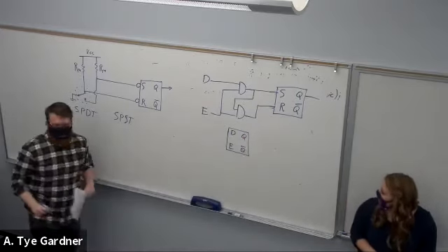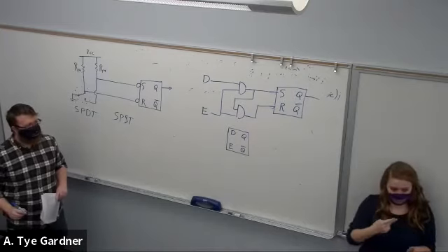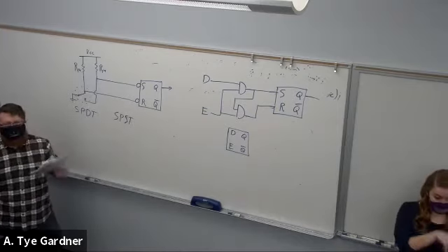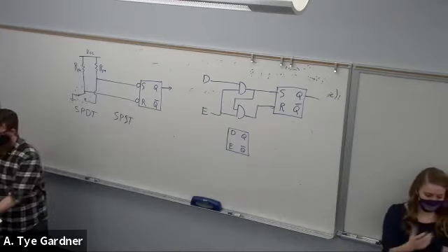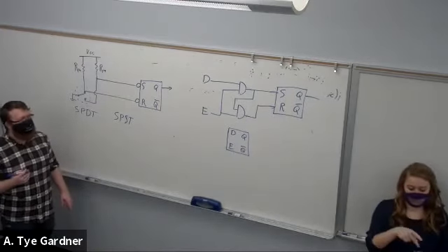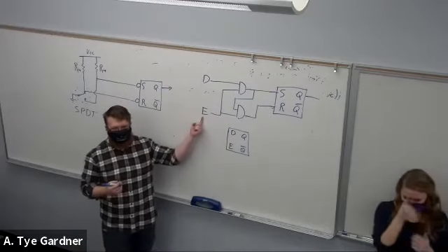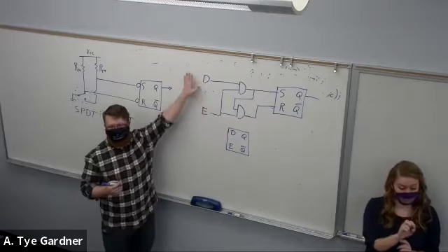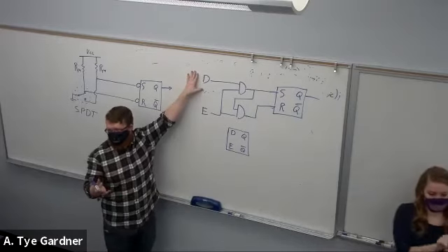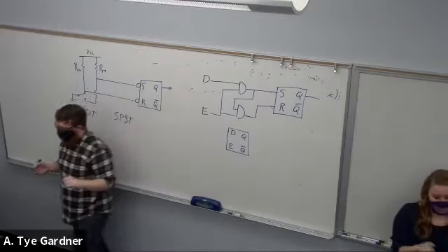That's our D-Latch. Where the enable goes in, we have the data. And this is also what we would like to call transparent. Because what it means is that as long as the enable is turned on, the output is going to immediately reflect data. There's whatever device delay there is, but that's it. It responds as quickly as it can.